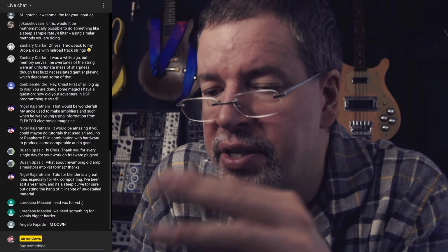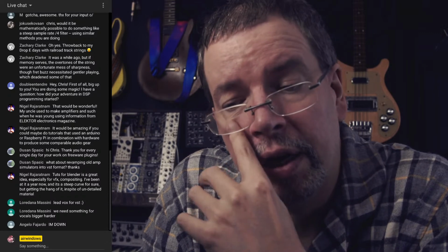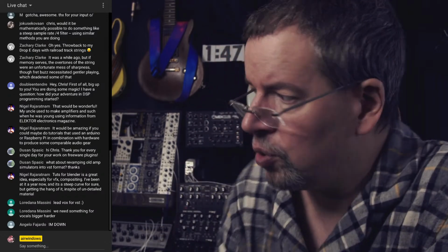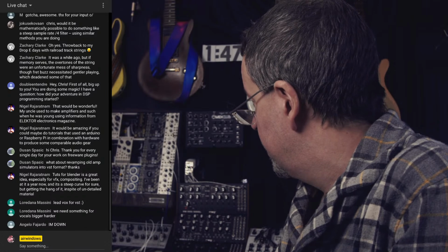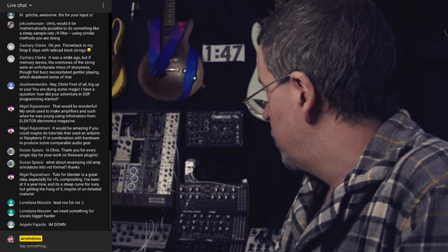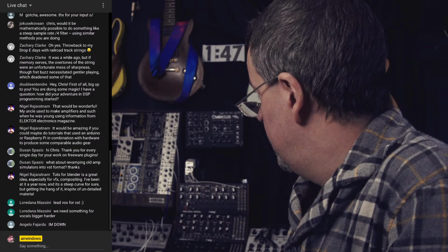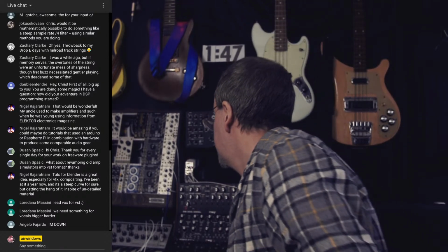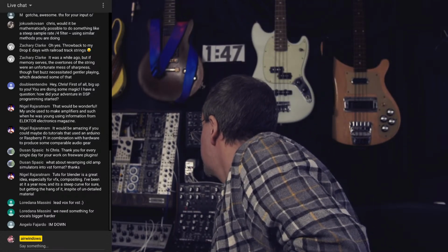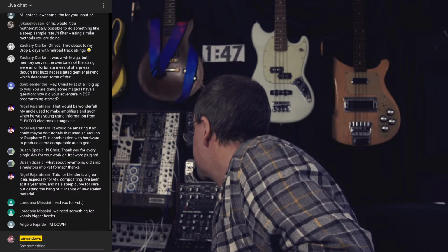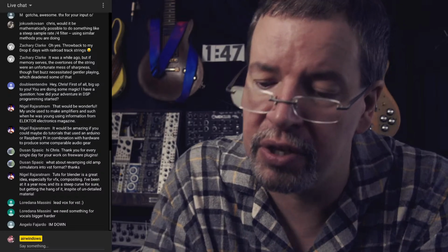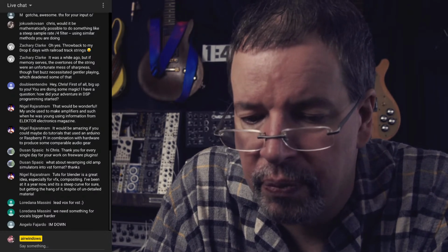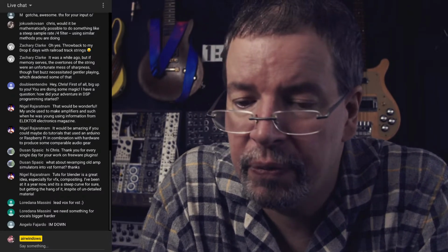But you just set something like that cycling, and then it'll keep cycling at whatever clock you give it, and give you the sequence of outputs. The thing about the Turing machine is that it has a variety of logic and stuff. Like, it's got additional outputs on its little pulses thing where it's 1 and 2, or 1 and 4. I think it's actually 1 and 2, 2 and 4, 4 and 7, or 1 and 2 and 4 and 7. So there's cascading stages of gates needing to be on. And those are AND gates, so those will trigger less often.